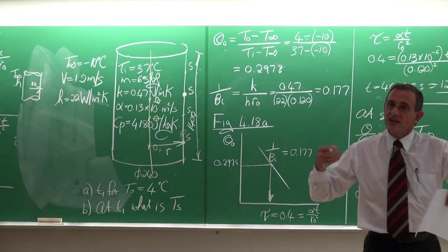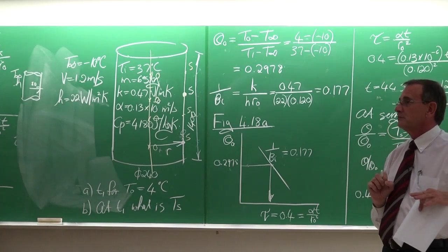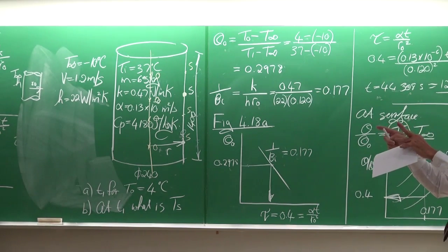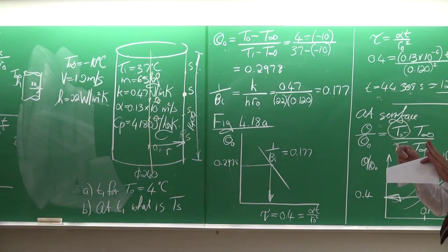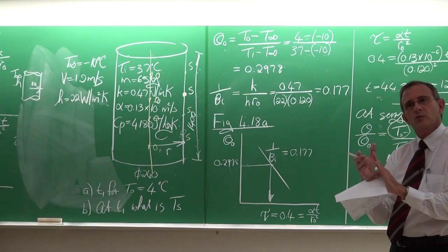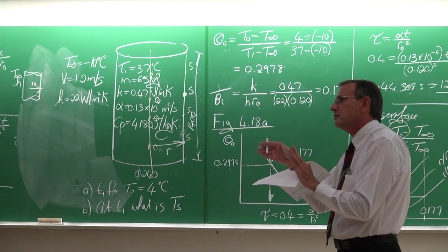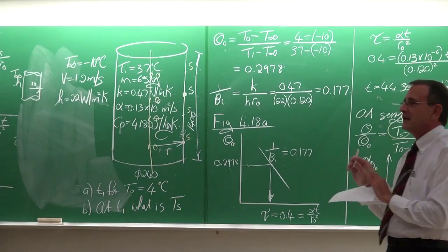Okay. So with any big body, and again big is relative, close to the surface, this wall, for example, of this lecture venue is maybe 300 millimeters thick. However, if we're interested in how the temperature changes in the wall, when suddenly we change the environment temperature and we want to know just the first few millimeters or microns in the wall, then this approach is valid.